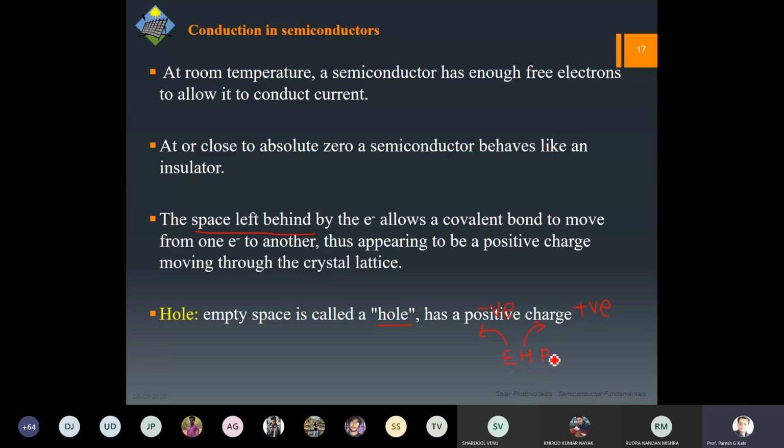And you can easily imagine why I want a special arrangement, because if electron and holes combine again somehow, then we are losing EHP, point number one. And if they combine, then obviously we do not have any carrier that will help in conduction. So our point is: create electron hole pairs, make them sustained, make them participate in the current, and once they have participated, finish the race or whatever, then you can combine them. So they should not combine before taking part in the conduction.